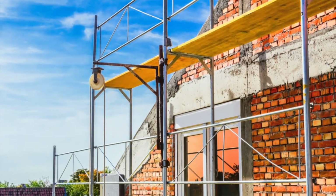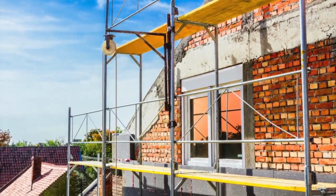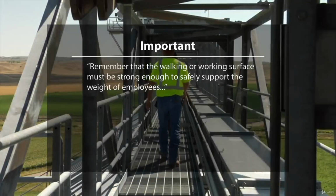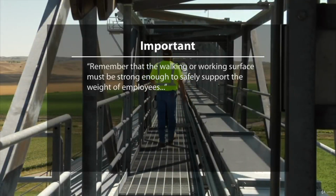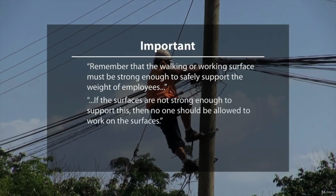In situations where employees could fall 4 feet or more, ramps, runways, and other walkways must be protected by guardrail systems. Remember that the walking or working surface must be strong enough to safely support the weight of the employees. If the surfaces are not strong enough to support this, then no one should be allowed to work on the surfaces. The employer's designated competent persons must conduct frequent and regular inspections to identify situations where potential fall-through hazards exist.